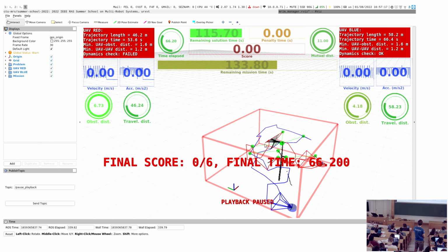If you rely on PIXHawk to control the attitude, PIXHawk somehow has to know the heading of the drone. With GPS, it's using the magnetometer, but when we are indoors and there is no GPS, PIXHawk can't know what the heading of the drone is. So for that, I would recommend going with attitude rate, but we can output attitude. That's totally possible. On the other hand, I would not go under attitude rate. I would not go for motor outputs from the NUC because that's quite dangerous. And getting the IMU data into the NUC at 250 Hertz, that's a tough job. So attitude rate is the sweet spot of the commands which you can send from the NUC to the embedded hardware. Thank you so much.